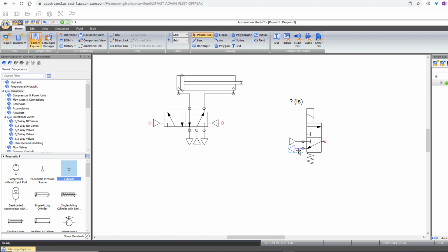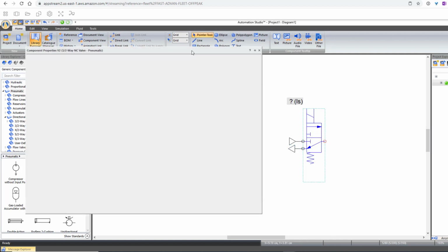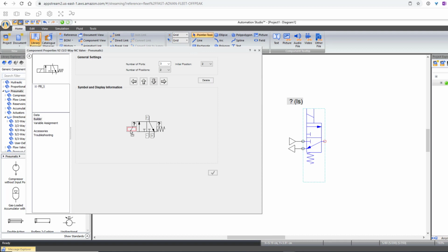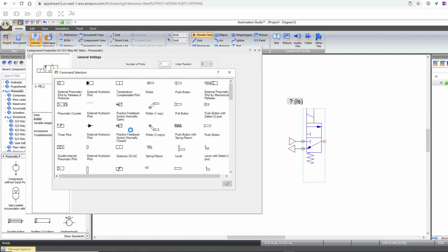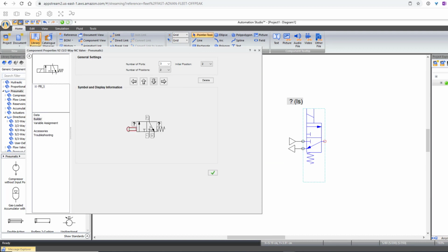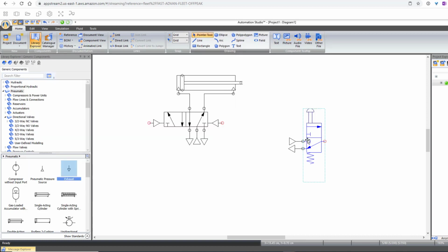Now, you know it won't be connected if this guy stays red. Now, what I need you to do is double click on this. I need you to turn that into a push button. Give it a sec. Here we go. I'm going to highlight this, double click it, and choose a push button, double click, and actually I can just close this and save the changes and it'll be a push button.